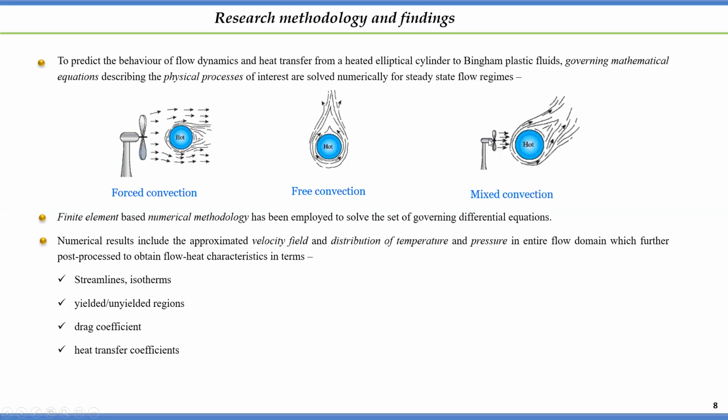But here, when you look at the direction of this flow, it will create different kinds of conditions in mixed convection itself. As we know, gravity acts in the downward direction, so of course buoyancy will act in the opposite direction to gravity. So when your flow is occurring in the opposite direction to gravity, that is in the direction of buoyancy, the flow current from the external flow media will combine with the buoyancy generated flow, and it will aid this overall phenomenon.